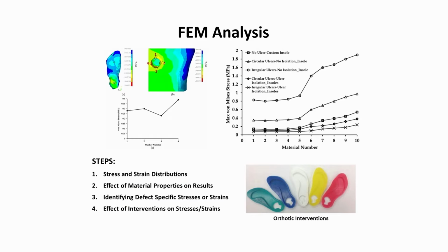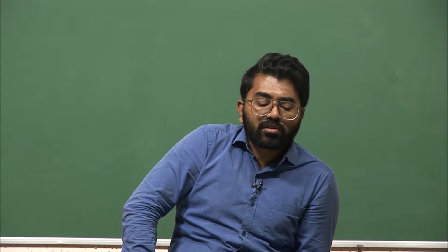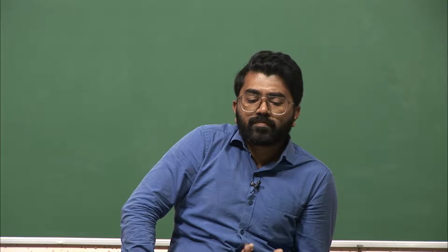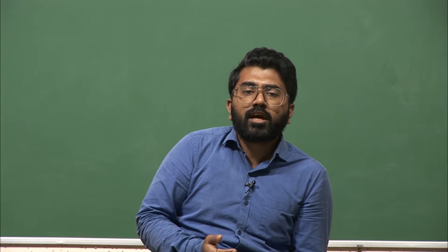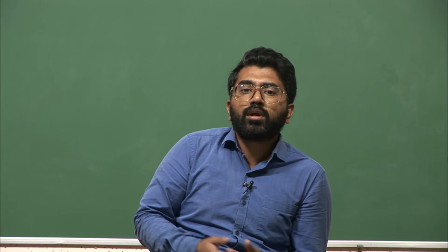So some of the key steps of this FEM analysis include understanding the stress and strain distributions, the effect of material properties on the results, and identifying defect specific stresses or strains. So are there certain locations where stresses are very high, which can be pinpointed. Effect of interventions on stresses and strains. So this analysis gives us an insight that we can use implants, we can use wearable devices and look at the effect of their loading on a particular person or generic population.